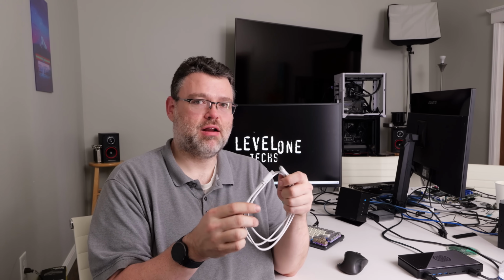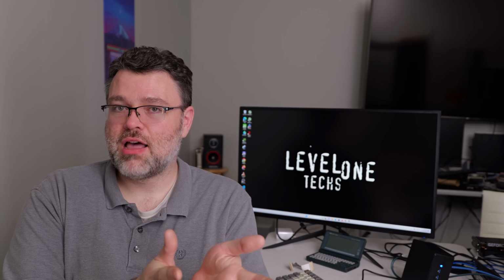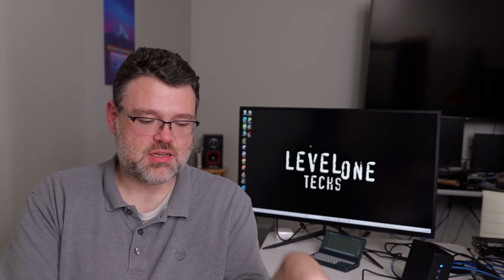But in a nutshell, know that on the physical USB-C wire, there's 4 high-speed pair, and that's what's doing all the heavy lifting. And the specification does actually allow for up to 8 high-speed pair, and you do have 8 high-speed pair in a 2x10 gigabit USB Type-C cable.